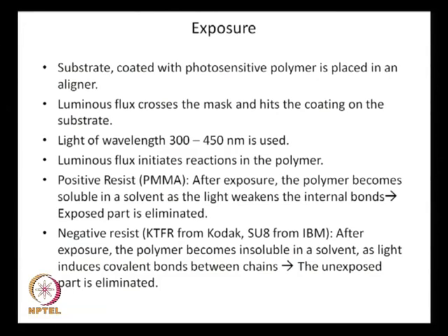the entire substrate, and then it would be taken to the exposure step, where a part of the polymer will be exposed to light. One portion would be the lit portion, and the other portion would be the dark portion, and then depending on where it is lit or dark, that polymer will be dissolved, taken away from the substrate.